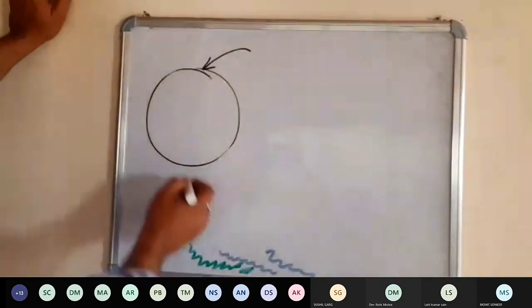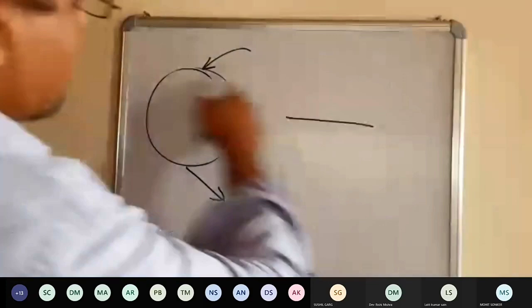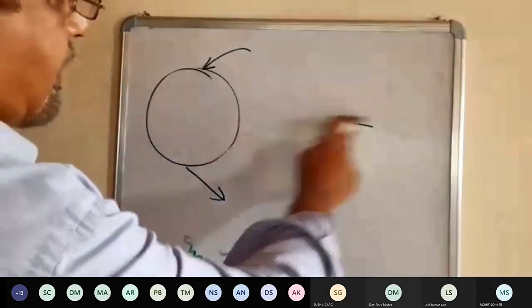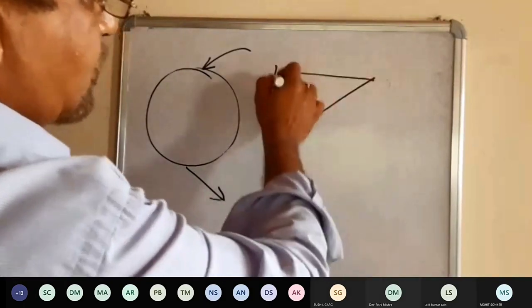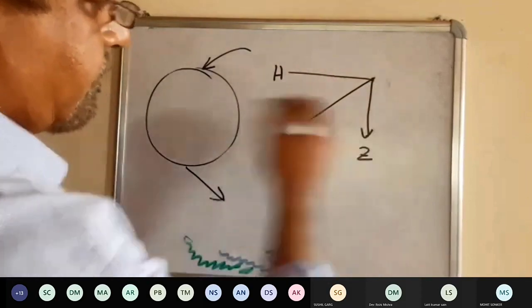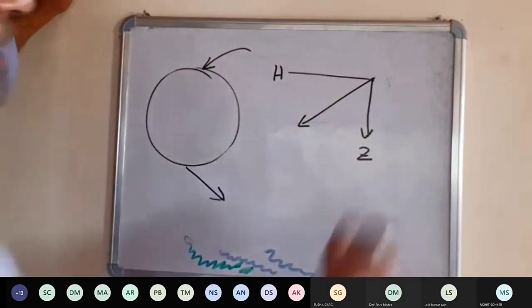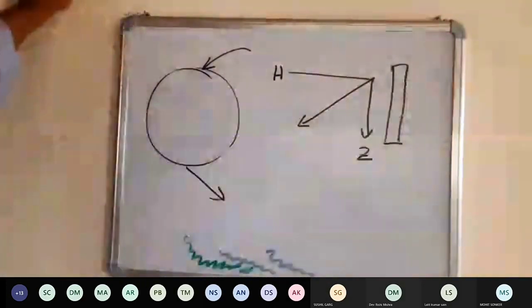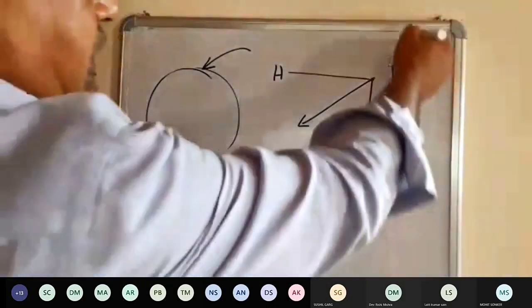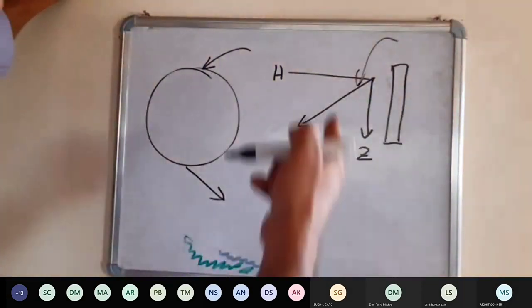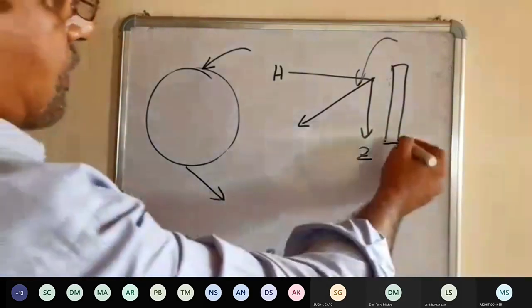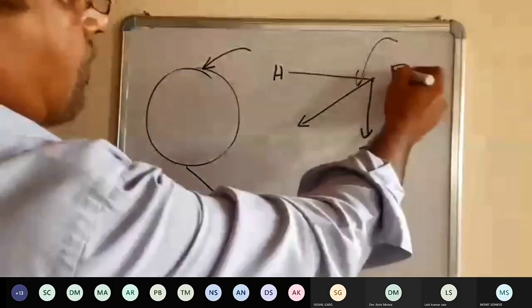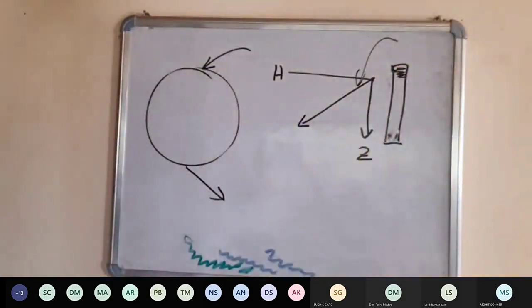As we know, the lines of force come in and go out here. In the North hemisphere, the total force is coming down like this, which can be resolved into H and Z. If this is the vertical soft iron, lines of force are created like this, so poles are created accordingly. This side will be the red pole and the upside the blue pole.